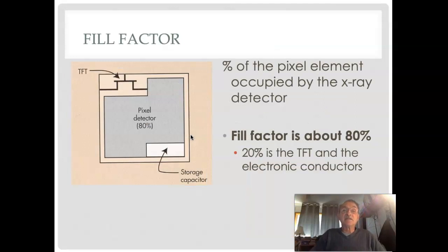Fill factor. This is a term that I've run into so often that my suspicion is you may see a question about what is fill factor in relationship to digital imaging. And the fill factor has to do with the detector. I'm looking at an individual pixel. And the gray portion of this pixel detector, this is the light capturing area.